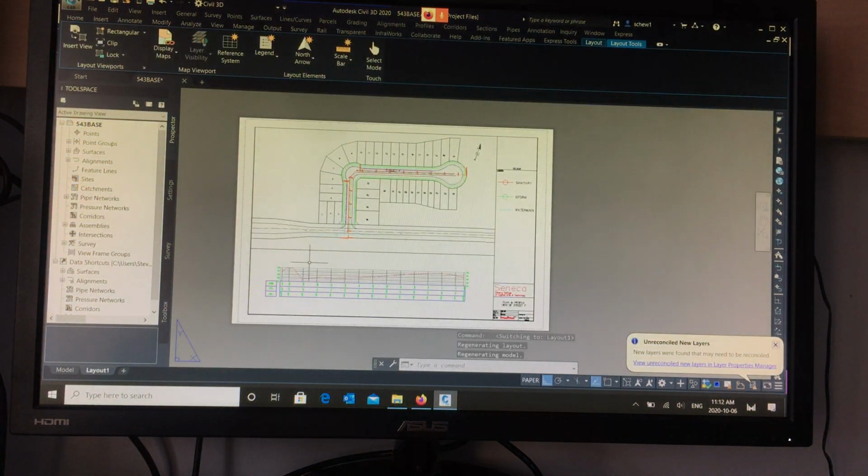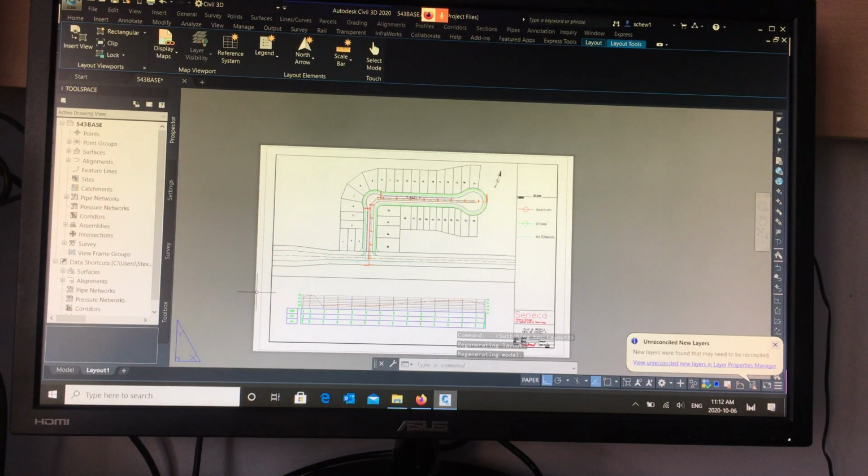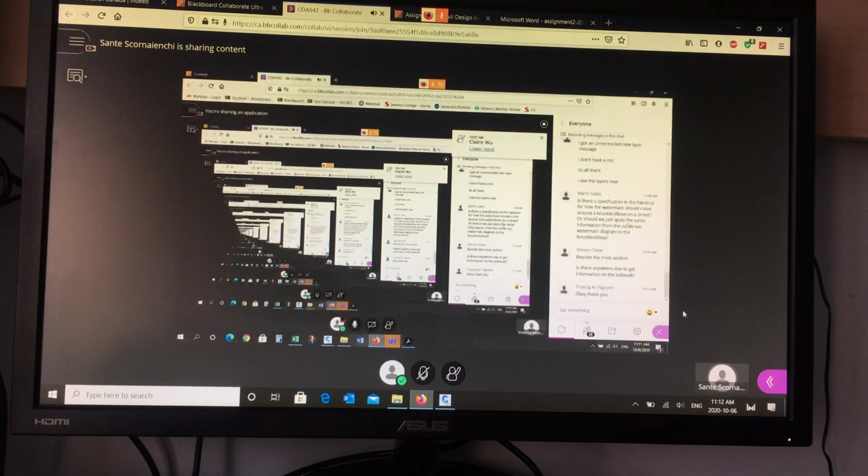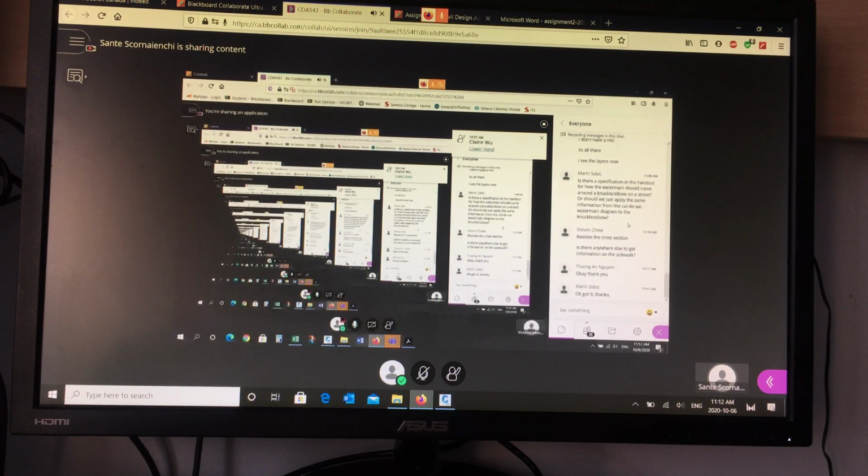Okay, and then you need to draw the loop in the cul-de-sac correctly based on the standard I gave you, a W7A, I believe. And then at the intersection, just extend it to the existing water main, and that's it. Right. So just draw the center line of the pipe. You don't have to label any of the bends or the T's or the hydrants. Don't leave anything out except the line. Okay. If you want the label for the size, you can. We're going to use a 150, but we'll deal with that kind of stuff next semester. Okay. It really is an AutoCAD exercise, not a Civil 3D exercise.